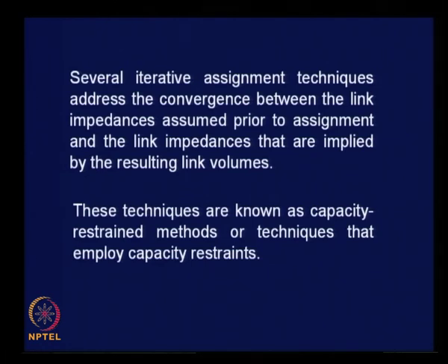There are minor variations, there are several approaches under the capacity restraint technique. We just talk about the general principle involved in the capacity restraint method of traffic assignment, which basically involves consideration of the assigned traffic volumes while estimating the travel time and the resulting minimum path tree that employ capacity restraints.